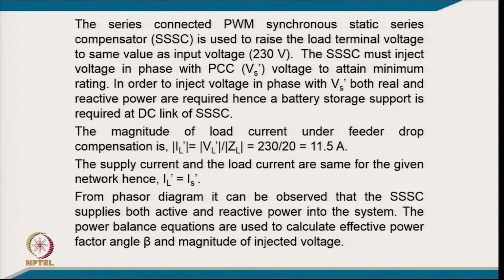Then the series connected PWM synchronous static compensator is used to raise the load terminal voltage to the same as the input voltage of 230 volt, and the SSC must inject the voltage in phase with the PCC voltage to attain the minimum rating. In order to inject voltage in phase with Vs dash, both real and reactive power are required. Hence, battery storage support is required at the DC link of the SSC.